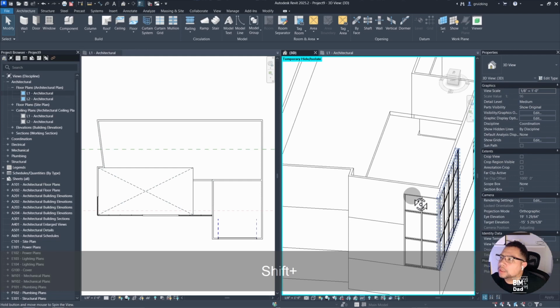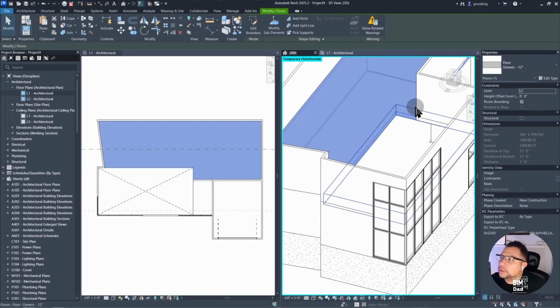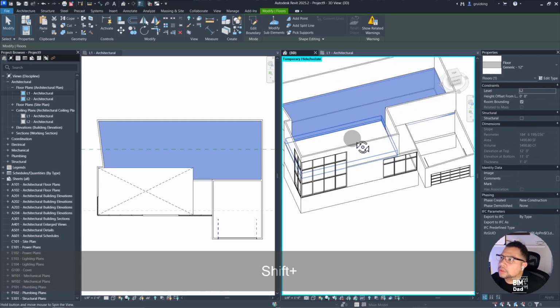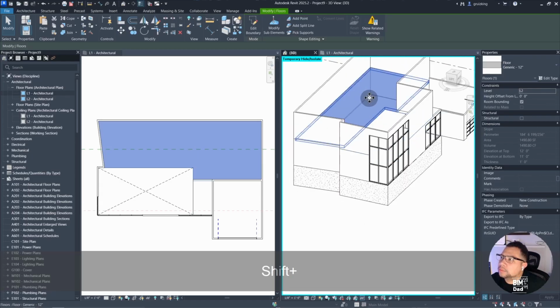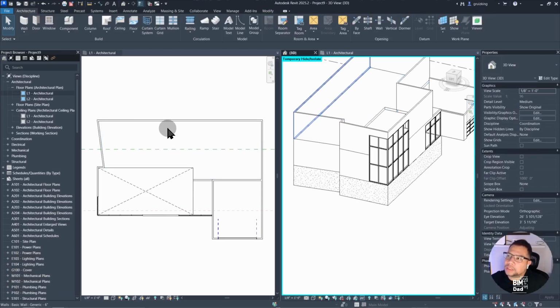There is an opening here, so potentially no ceiling there, but at the moment we just simply have a floor that's covering most of the plan there. So we're going to potentially need a separate ceiling modeled. This can be useful to, one, accurately capture dimensions. Two, if you happen to download a family for lighting that's ceiling hosted, now you'll have the ability to host it. So as far as modeling it, pretty simple.